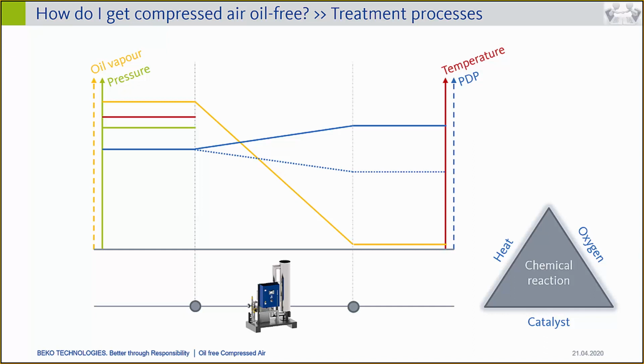So that means, in any case, if there is a constant low dew point required for the oil-free application, you need an additional dryer after the BEKO. There's no question about that.